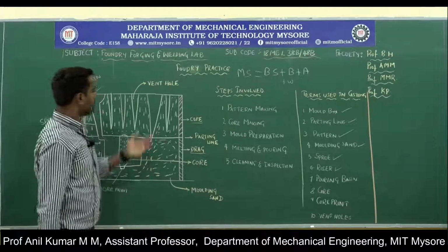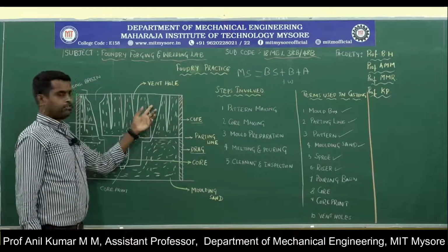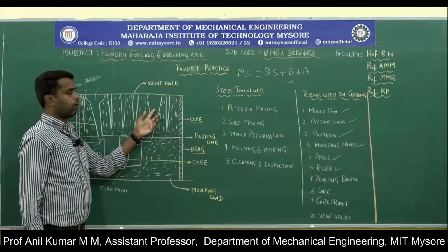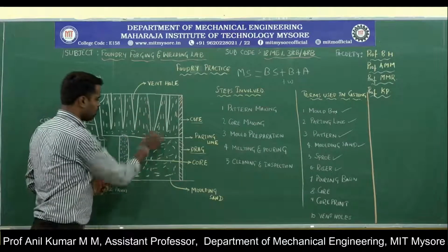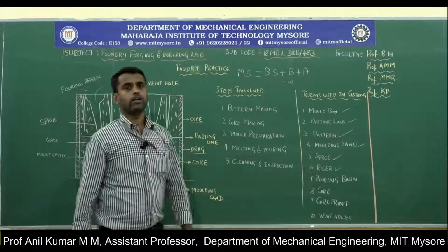Next, riser. Riser is a vertical passage which stores the molten metal while pouring, and then it supplies the same molten metal into the mold cavity during solidification.